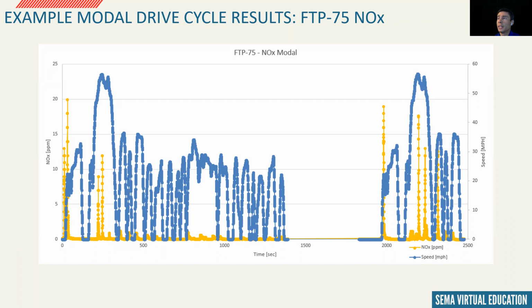When we talk about transient fuel control, we can modify this by calibrating our transient fuel gain and time constants during tip in and tip out events, accel and decel. The gain will be the fuel mass, for example, and the time constant is the transition rate and time.